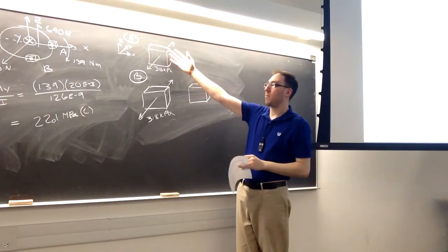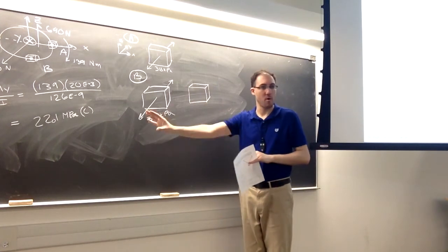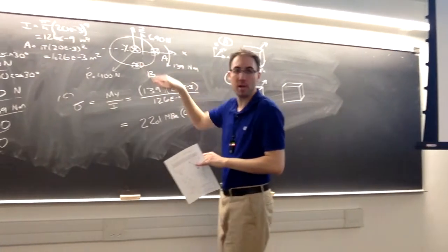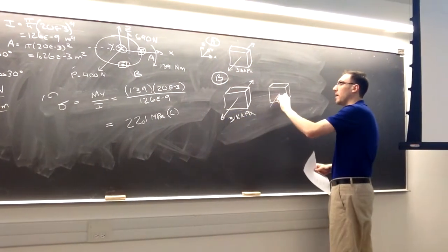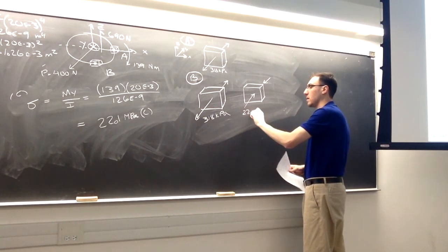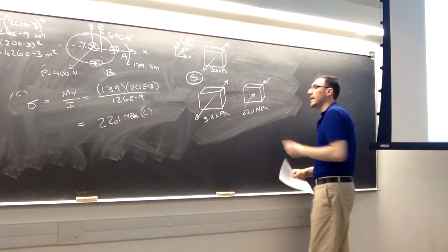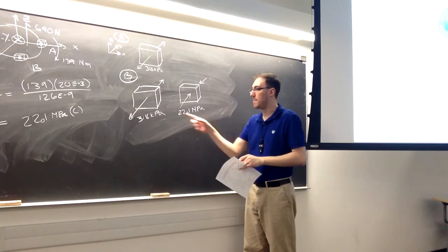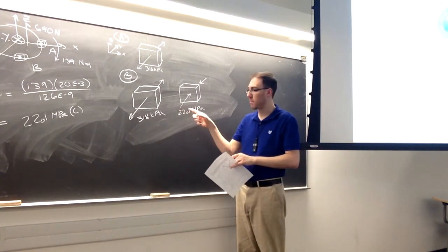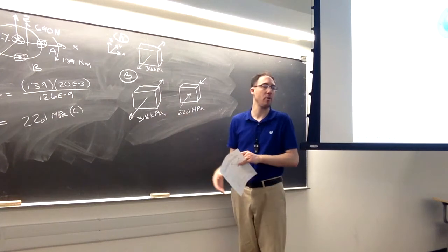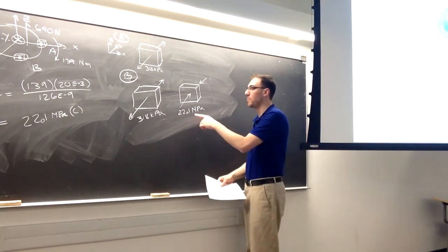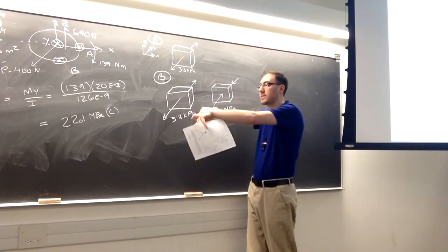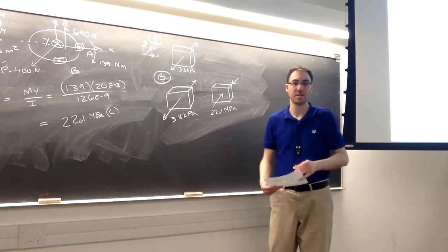So A, we don't add any more stress to. B, we now will superimpose also this stress, a compressive stress now, also on that same plus or minus Y face, 22.1 megapascals. It's compressive, so it's pushing in on those surfaces. And notice when I'm drawing these, I'm not putting ever negative numbers. I'm just making sure the arrows point in the right direction. So it's 22.1 megapascals, but pushing into the surfaces. This was 318 kilopascals pulling out on those two surfaces.